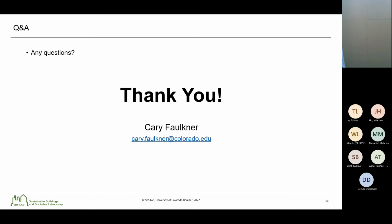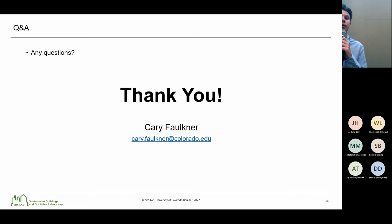Yeah, that's a great question. So the question was, the MERV efficiencies are based on different particle sizes and are different for different particle sizes. And so in this case, we assumed a constant particle size of 1 to 3 microns, and that's how we got those efficiency values. We did not consider any distribution of particles, but I think that is very interesting work that should be studied because the viral particles can vary in size and have some sort of distribution.